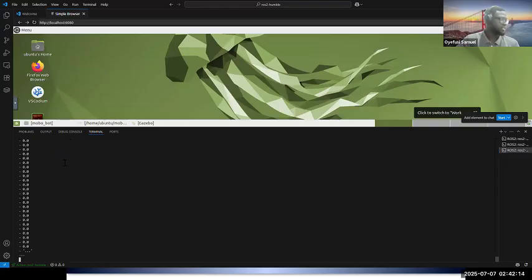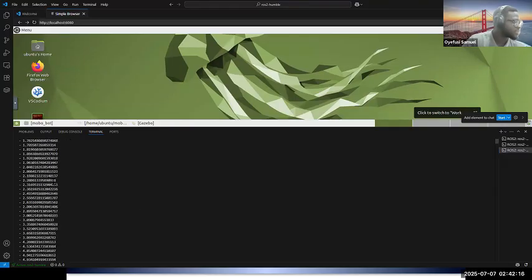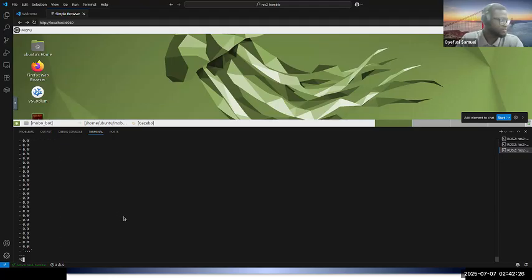We're going to see the messages now. Can you see the zeros? Can you see the points? You can see the LiDAR as it's rotating, it's showing us the different readings. So I'm going to stop this so you can see the different values. I'll just stop it with Ctrl C.